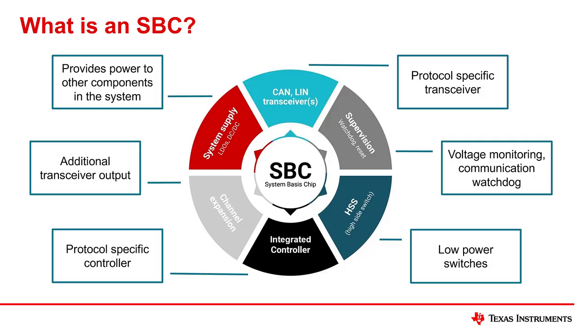These can be used in place of discrete load switches for lower current applications. At the bottom of the wheel, it shows that some SBCs will also include an integrated protocol controller, allowing more flexibility in the subsystem's main controller. Some SBCs will also include specialized logic outputs that can control other discrete transceivers, allowing for channel expansion to be facilitated by the SBC itself. Finally, all SBCs will have some voltage regulation abilities, either in the form of LDOs or switching converters, such as a buck.